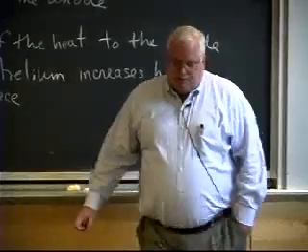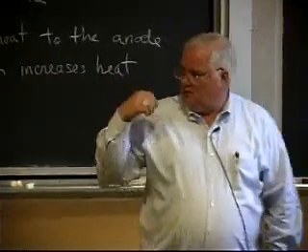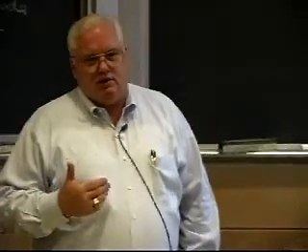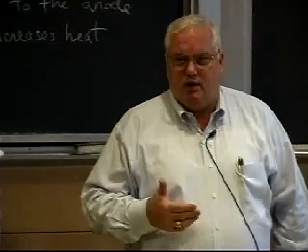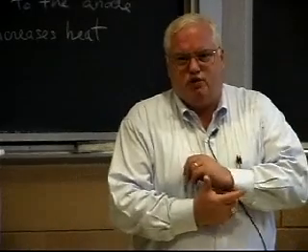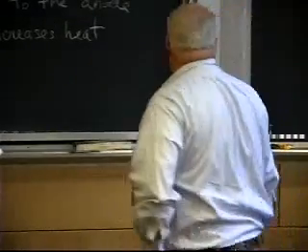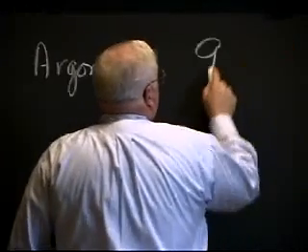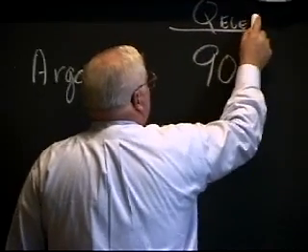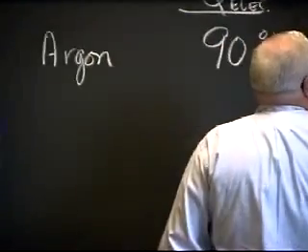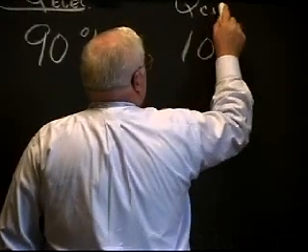We also started talking about different shielding gases, and the 70 and 30% applied basically to argon shielded arcs, which is the most common. But if you use helium, you can get a substantial increase in the melting efficiency. We made a little table: if I had an argon arc of whatever current rating, 90% was electron heat and 10% was convection heat, conduction plus radiation.